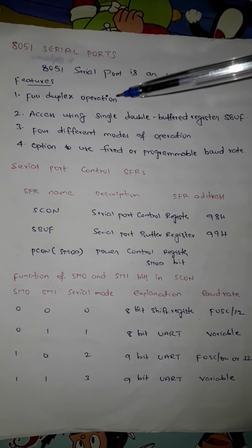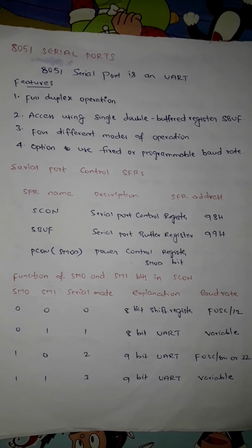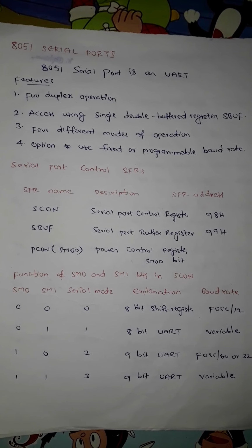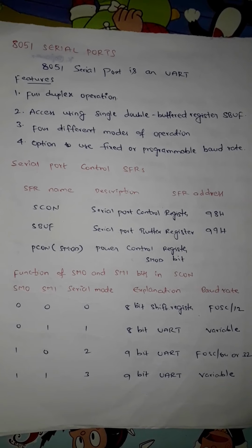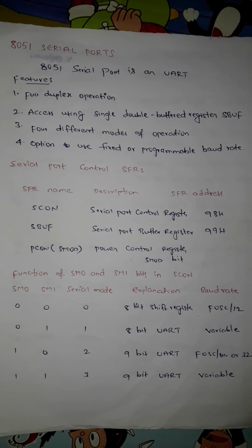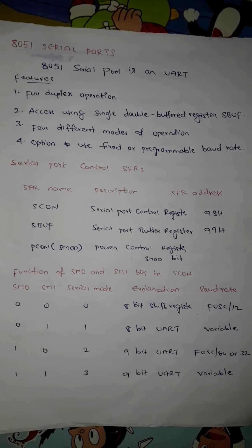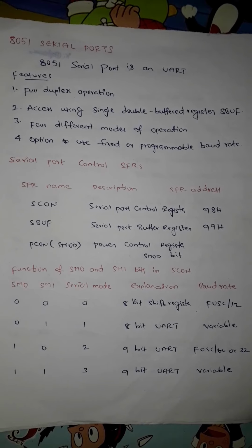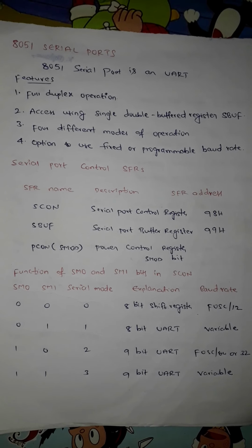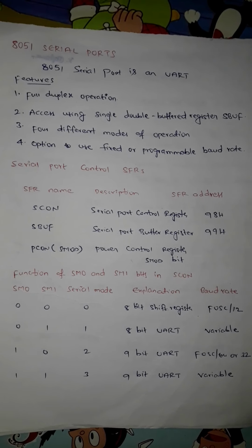Let us look into some of the features of the serial ports. So one is the full duplex communication. The 8051 serial ports support full duplex communication. So they have two separate lines for transmitting and receiving the data. So it supports full duplex communication, and also it has a double buffer register.